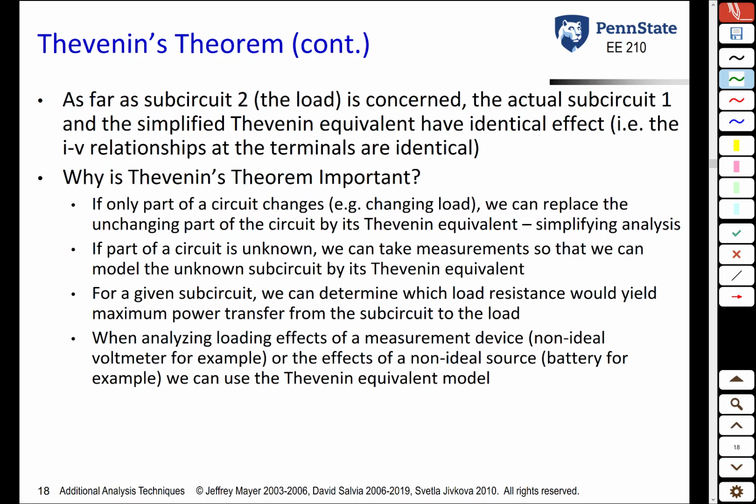Third use of Thevenin's theorem is what we call maximum power transfer. We're going to see this towards the end of the packet, that as you change your load resistor, it changes the voltage across it, it changes the current through it, which means it changes the power absorbed. And you can use Thevenin's theorem to determine what the absolute maximum power that that load can absorb is.